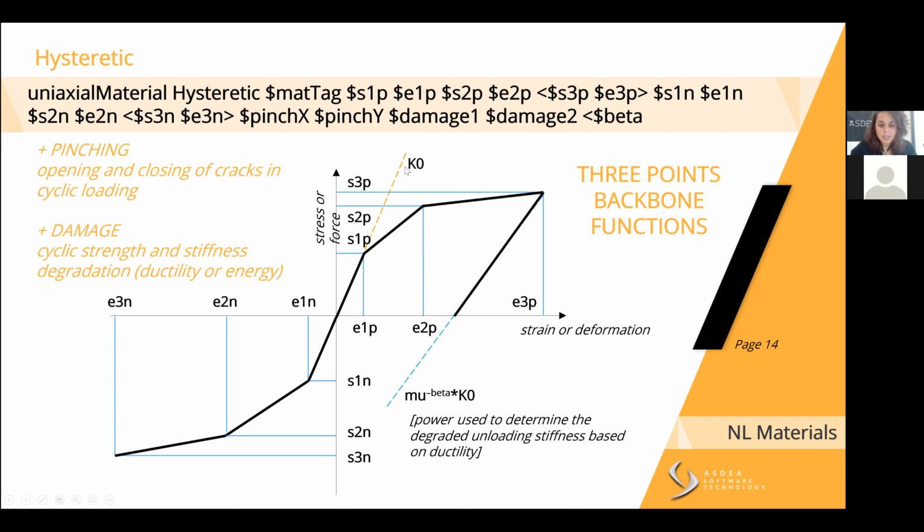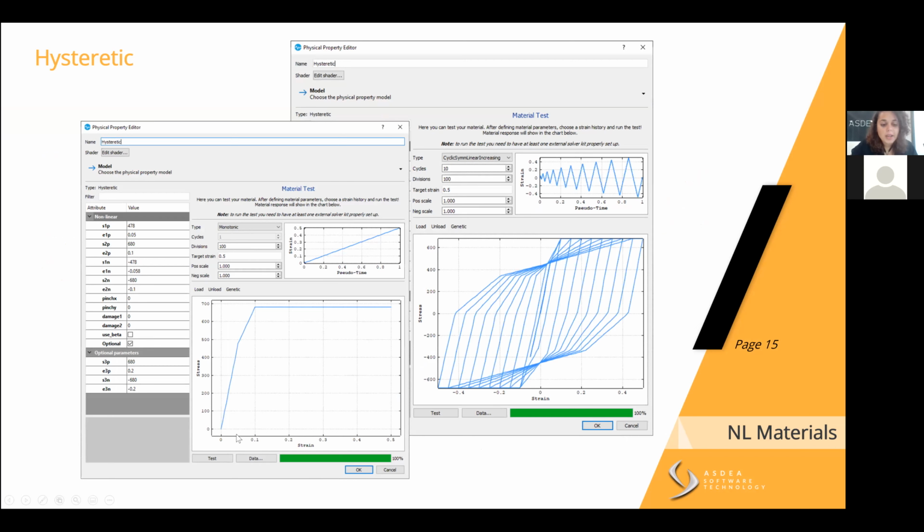So what you actually come up with is you don't have to input the stiffness. Stiffness is computed inside. And this stiffness is used, with a beta factor applied to the ductility, in order to define the stiffness of the unloading branch. What we obtain here is, for example, if we want to model a simple shear cracking and then shear maximum strength, this is actually done for a steel, but it's the same for any other type of nonlinearity that you want to model.